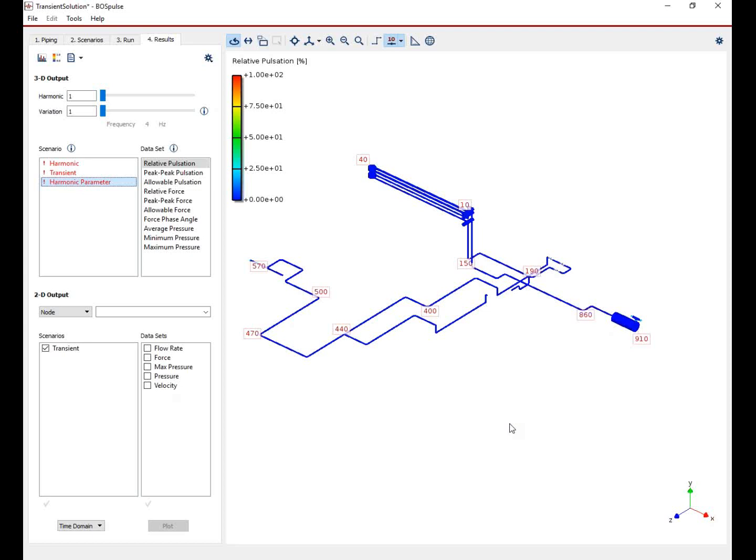But if you really do not have an isometric, there will be holes in your system, and especially if you have a lot of isometrics, that might be difficult to find out after you import it. But even with 1,000 isometrics, if you miss a couple and they don't connect that well, it still saves a lot of time to model it, because modeling 1,000 isometrics by hand is going to take you weeks, and it took us around a week to import them. So I think it's a very nice feature. I hope that answered your question.